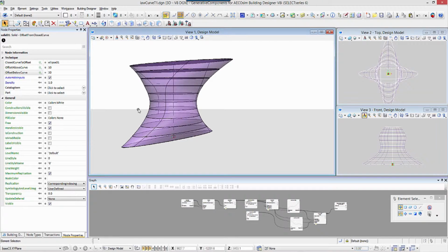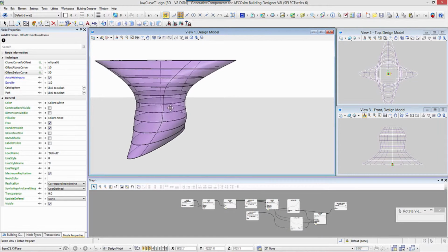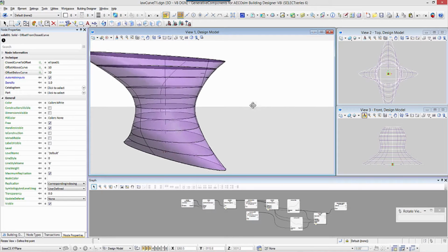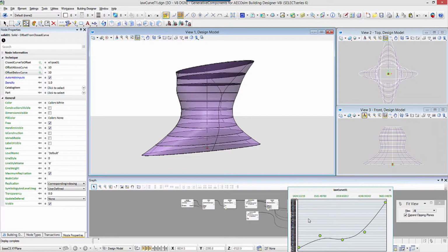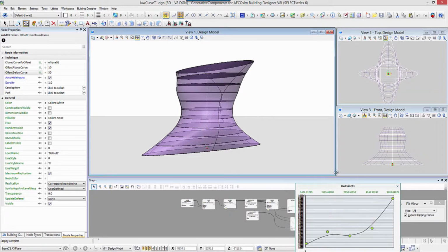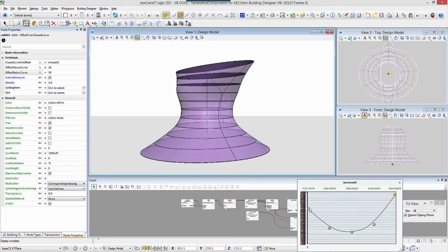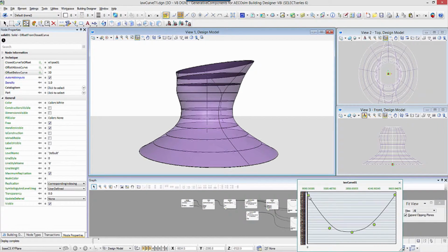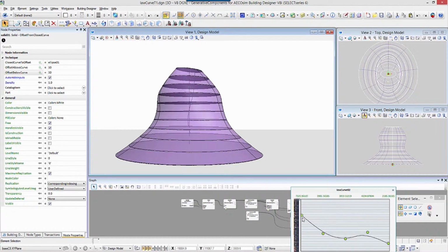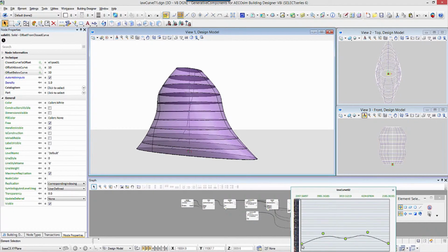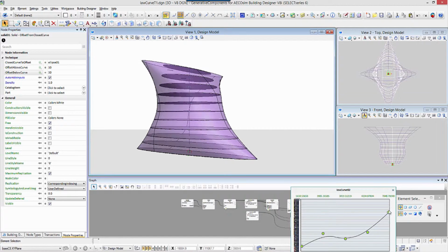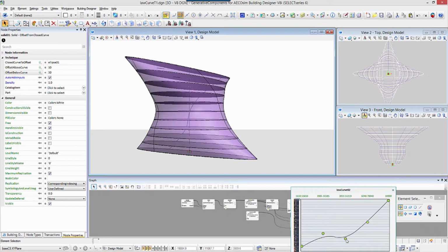That was about simple buildings, normal box type buildings. Now let us see a simple case of a curvilinear tower. In this case, the floor plates of the tower are elliptical in shape, and we are controlling the radii of the ellipses, that is the primary and secondary axis radii of the ellipses, using the law curve tool. We are simply connecting the dimensions of each floor plate with the law curve control points, and this allows us to control parametrically the silhouette of the building.